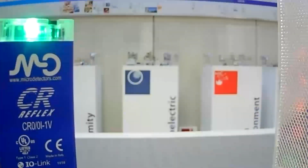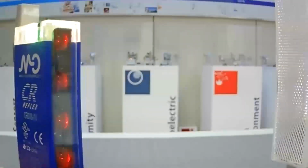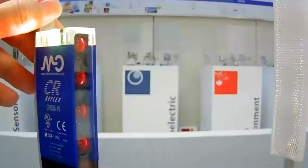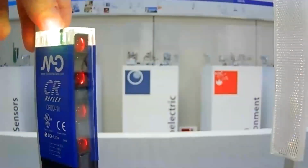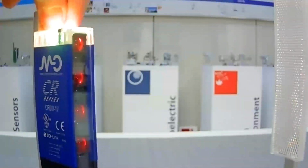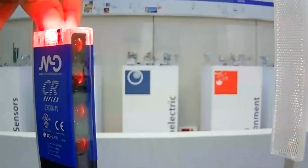In this case, we have made the long teaching, and you can see that it's very easy to detect even a transparent object. By the teaching button it is also possible to adjust the number of beams that I want to keep active. In normal operation, you see that we have 4 beams on the photocell, so we have 4 emitters, but using the teaching button, it's very easy to adjust the number of beams that I want to exclude. And this could be because we have a fixed part of your machine on the top, on the front. So you have to press the teaching button.